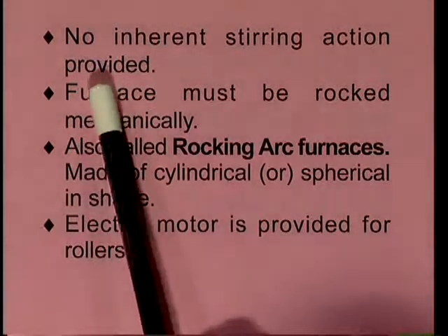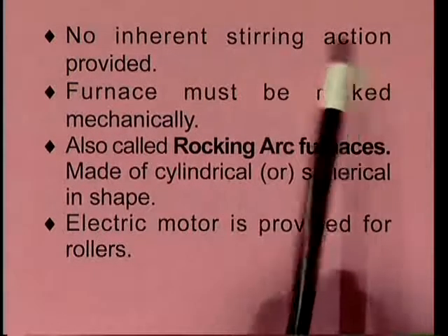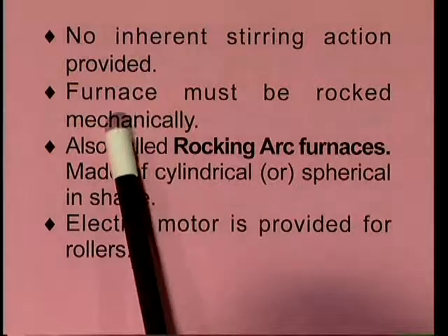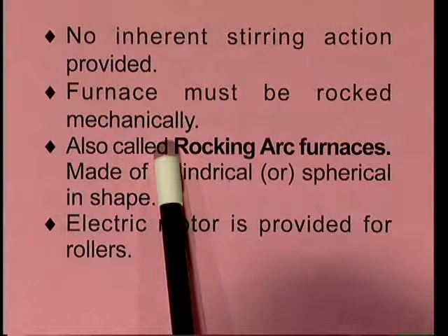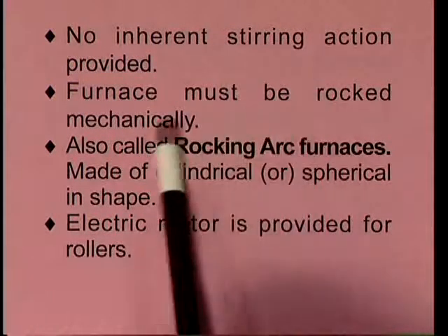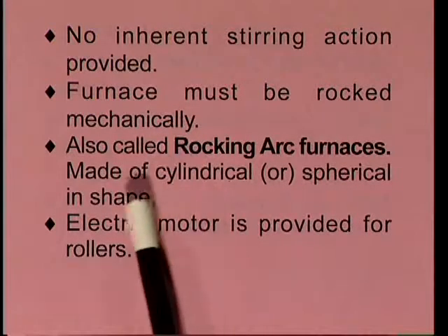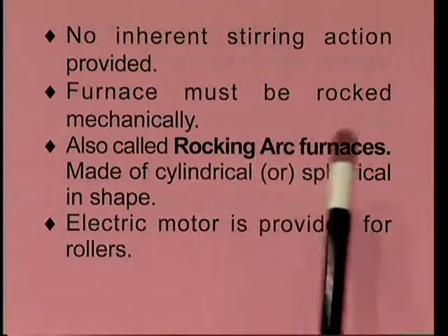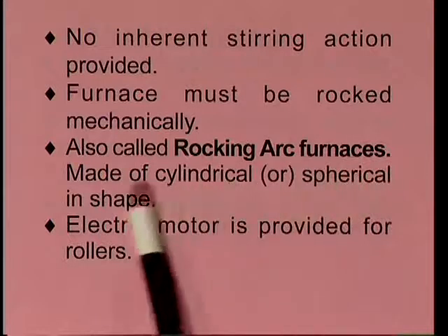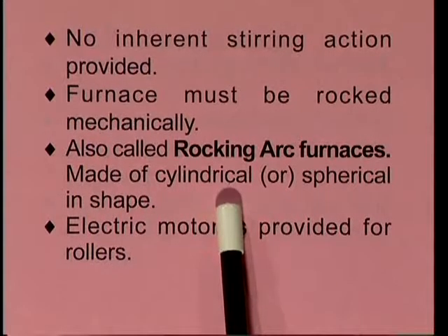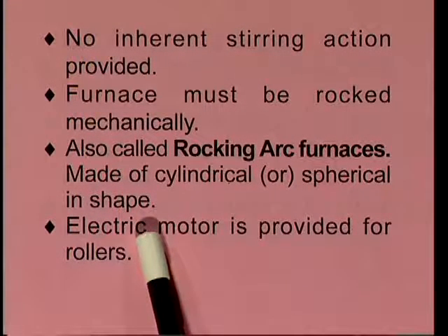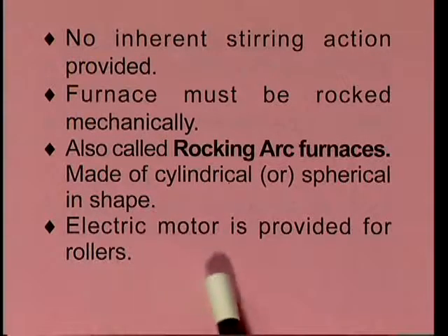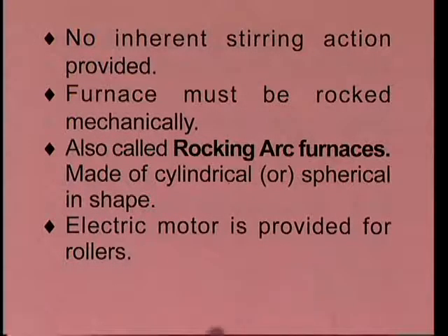In indirect arc furnaces, no inherent stirring action is provided. The furnace must be rocked mechanically because there is no stirring action, so these are also called rocking arc furnaces. These furnaces are cylindrical or spherical in shape. An electric motor is provided for the rollers.